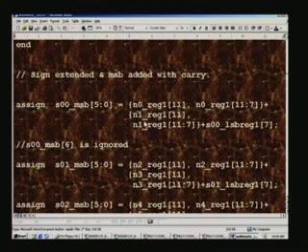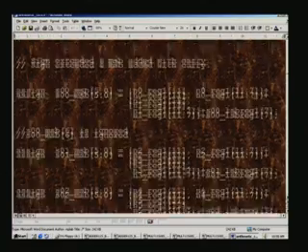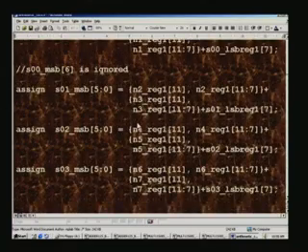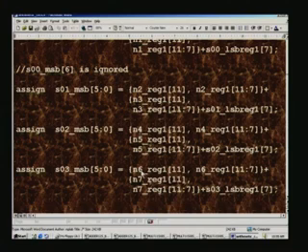To this we have to add the second number, and that also follows the same standard style. For example, this is the sign extended bit, and this is the actual MSB bit of N1, and to this we should not forget to add the carry resulting from the LSB addition, which is available here. This was the last bit in the final result of LSB addition, and that should not be forgotten. The same is the case for other pairs of numbers, for example N2, N3, then N4, N5, then N6, N7.